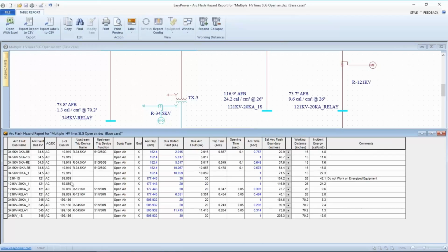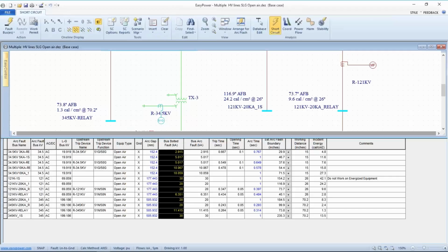But you can see where I've set up a time delay for a bus limit. I don't have the specificity or the details on that particular calculation, but any place I have the relay doing its function, we can see both the overcurrent results and the ground results for that particular bus. And this will vary based upon where I have my grounds in the system. So that's how it's done.